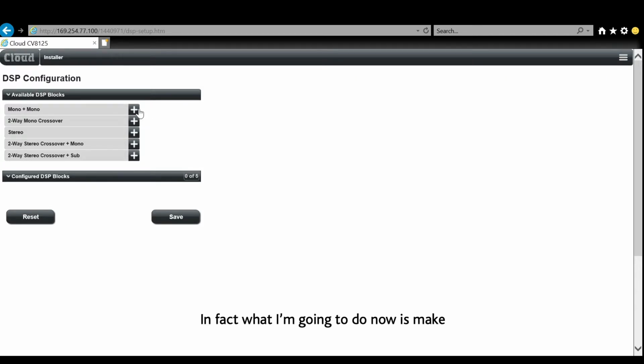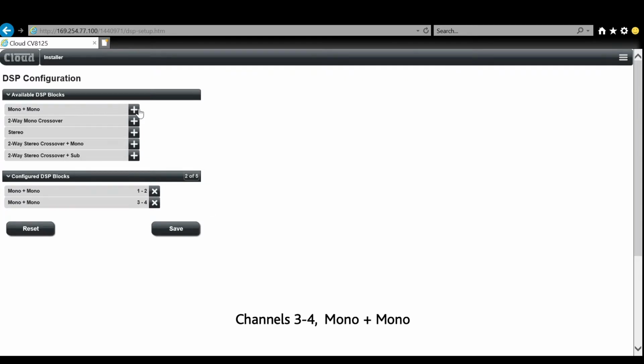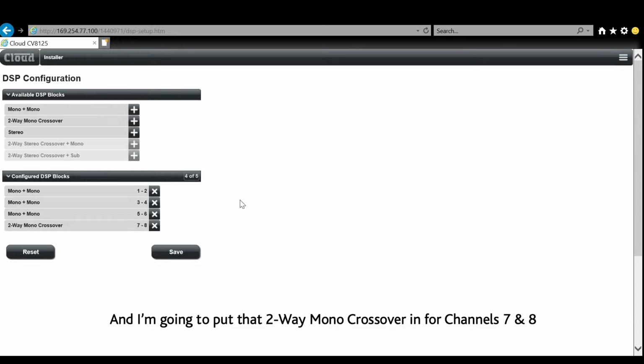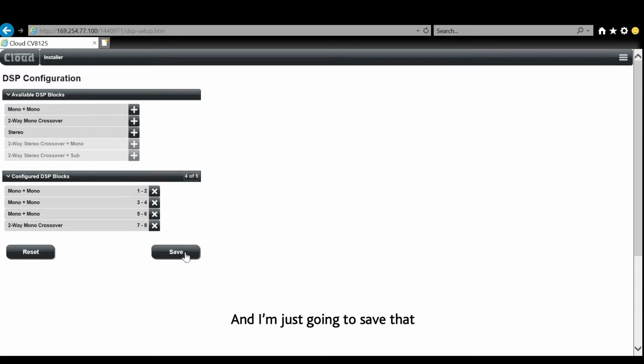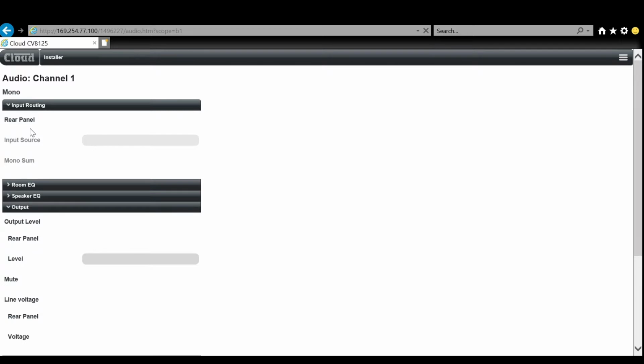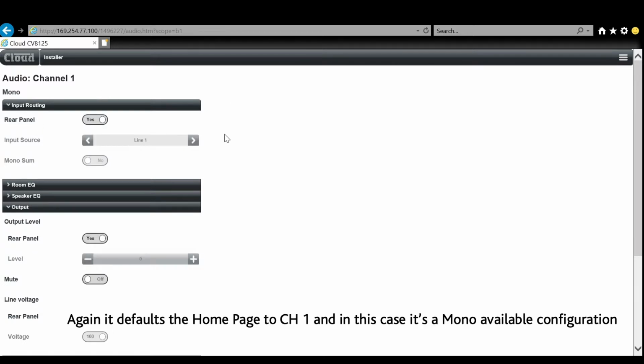What I'm going to do now is make channels 1, 2 mono mono, channels 3, 4 mono mono, 5 and 6 mono mono, and I'm going to put that two-way mono crossover in for channels 7 and 8. And I'm just going to save that, and we have to reboot, and there we go. Again, it defaults the home page to channel 1, and in this case it's a mono available configuration.